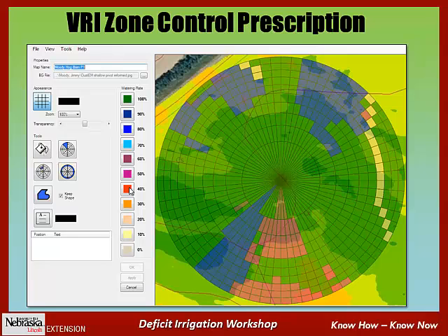Now, how do I pay for this? It's not the pumping of the water. You're going to pump all the water. The difference is now, what's the value of that water by being able to have an extra inch of ET up on the side slope or the hilltop? And right now the slope of a yield ET line is about 13 bushels per acre inch for corn. So if I can get 13 more bushels per acre inch on the side of that hill, pumping the same amount of water, that's a whole bunch more money to pay for some new improved technology than there would be if all I'm doing is looking at my pumping cost.